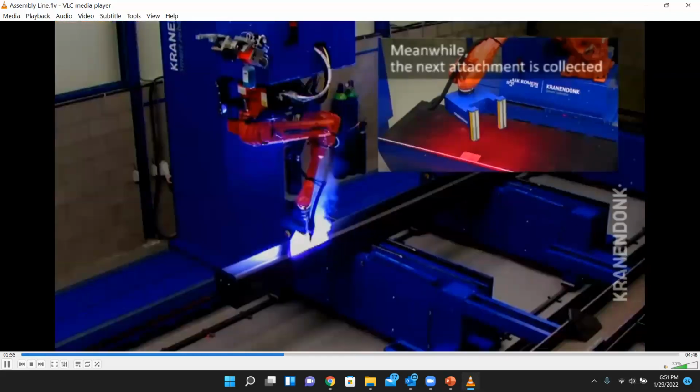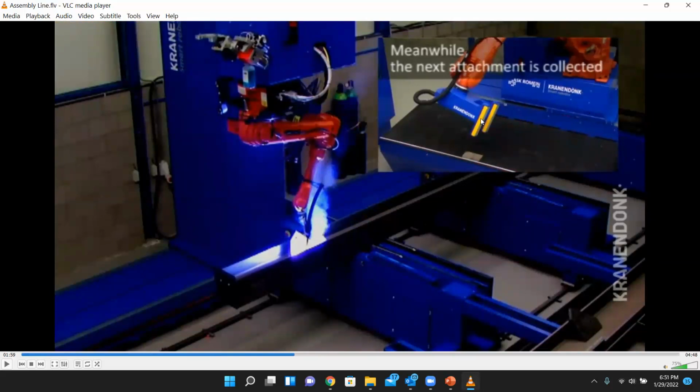So when you have multiple robots, right, working in the same workspace, now see the other robot, right? The other robot has to pick up the second block, which is here, right? While the second robot is doing the welding, the first one has already started the work. So it has a vision system to figure out where the object is. This metal piece can have different orientations. So the robot needs to pick it up in the right orientation. In order to pick up in the right orientation, the robot needs to know at what orientation the object is placed. So that is why it uses the vision system.